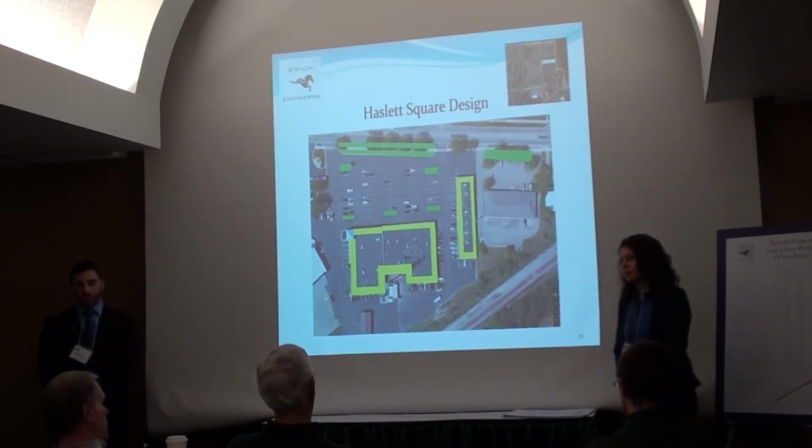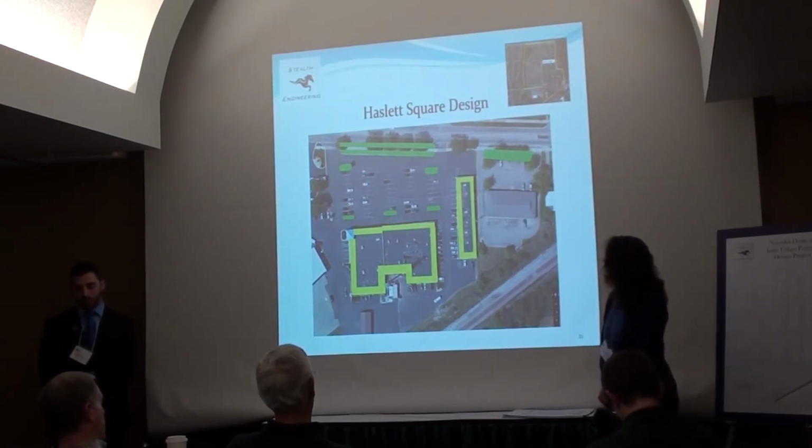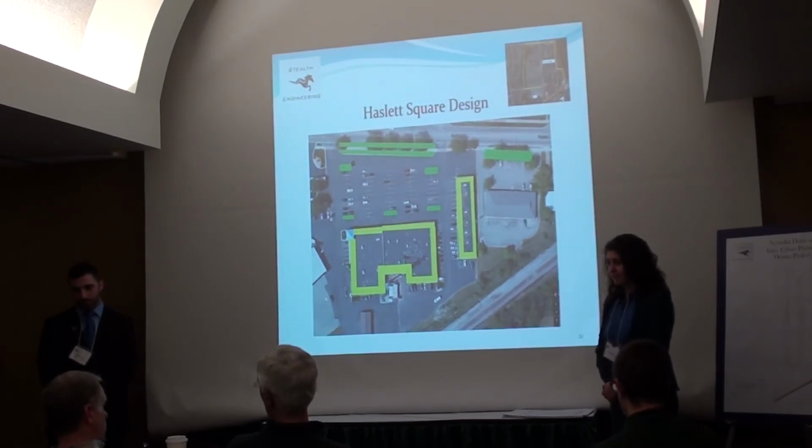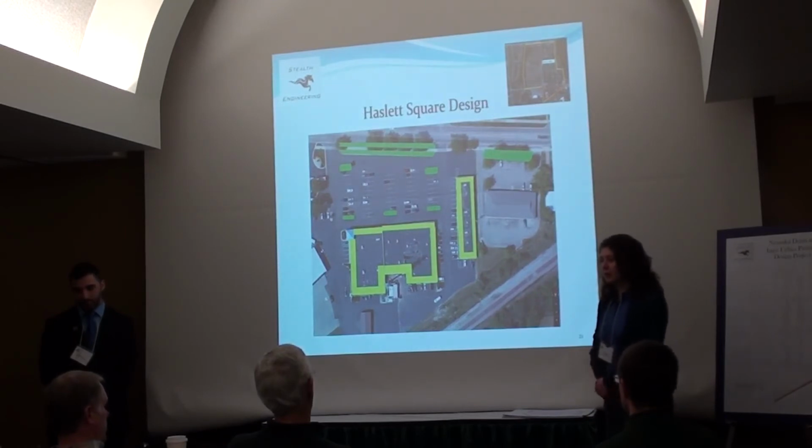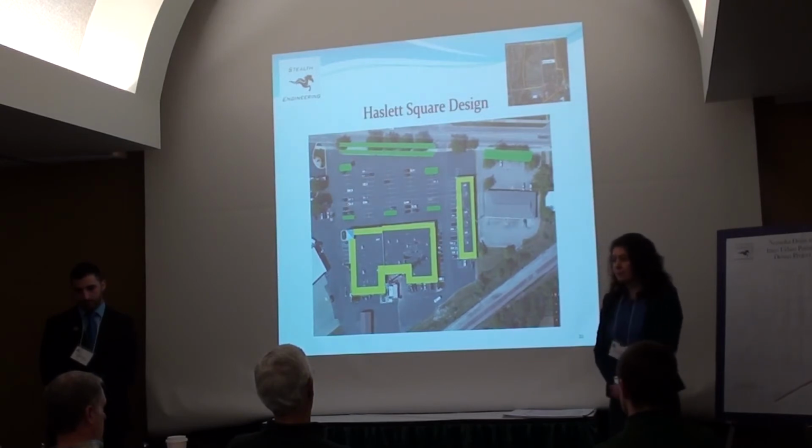It would not impose, if it's designed for snow properly, which I'm assuming it would be, able to handle all the weight. Do you know that the load you're imposing with that water is equal to or less than any snow load that will be imposed? I don't have the numbers, but I know from my experience that the snow loads would be much heavier.